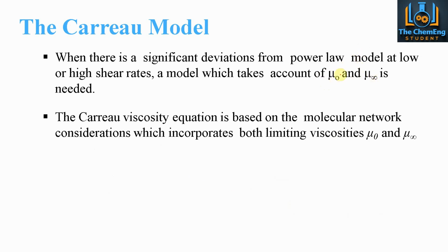So the power law doesn't actually account for these terms. These are the extreme values, i.e. the very initial viscosity and the infinite viscosity. Now, the Carreau viscosity model is one which is based on the molecular network, and it considers the limitations in terms of the initial viscosity, the zero viscosity, and the infinite viscosity. So the Carreau model is one of the first ones that we would consider on a chemical engineering program.